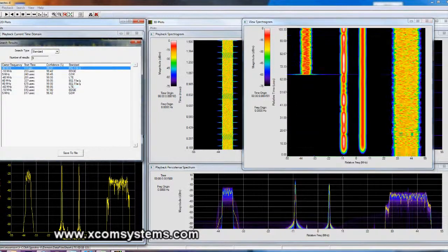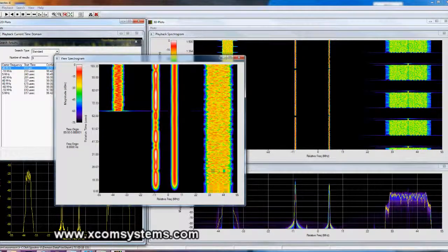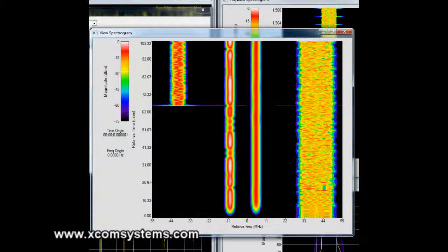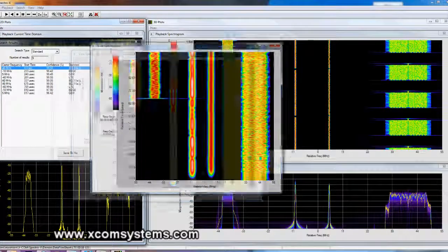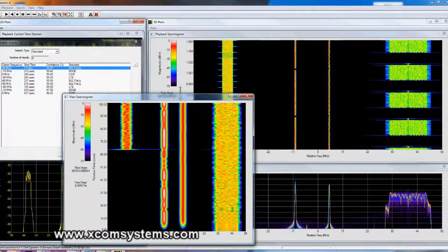I can equally look at, for example, what it's telling me is an 802.11 signal, centered at 40 megahertz, and sure enough, it begins the enhanced display of the waveform that it found, beginning with the training sequence of an 802.11 waveform. And similarly, it has found LTE, GSM, Edge, as well as the wireless LAN carrier of interest.